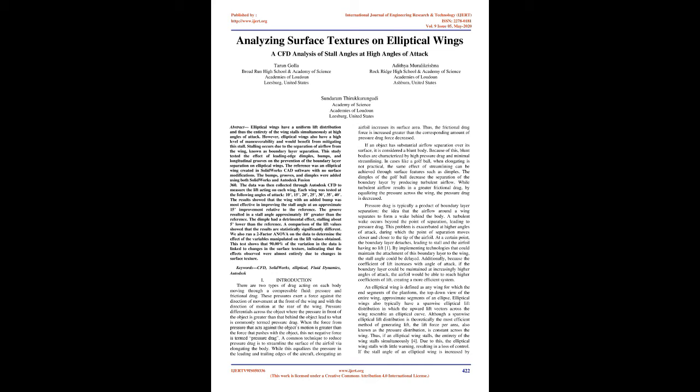The groove resulted in a stall angle approximately 10 degrees greater than the reference. The dimple had a detrimental effect, stalling about 5 degrees lower than the reference. A comparison of the lift values showed that the results are statistically significantly different.